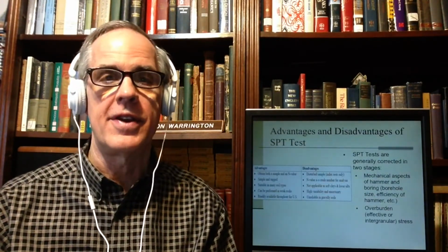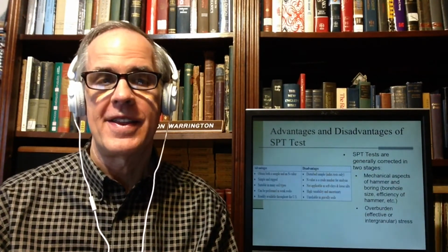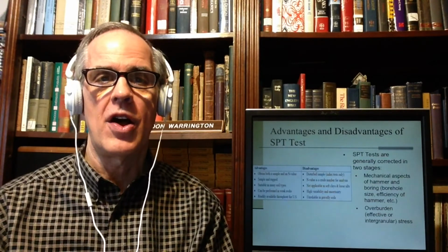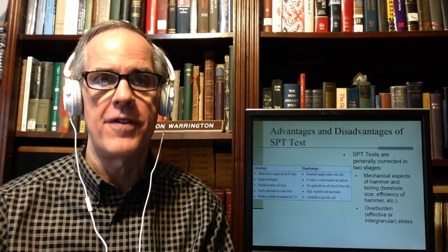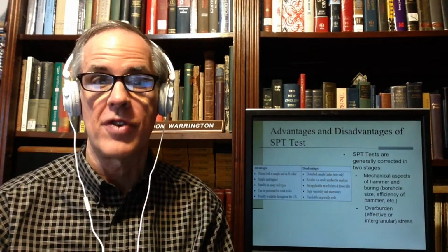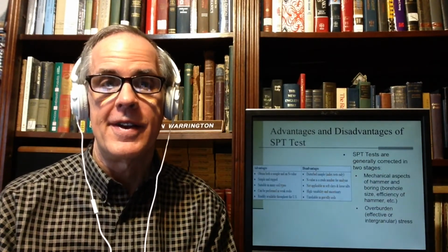And that difference can be significant. And that's been probably one of the things that has plagued SPT tests for years, is the fact that the results have not always been consistent, and the apparent efficiency has not always been consistent. Short stroking it will give lower apparent efficiency, and that sort of thing.